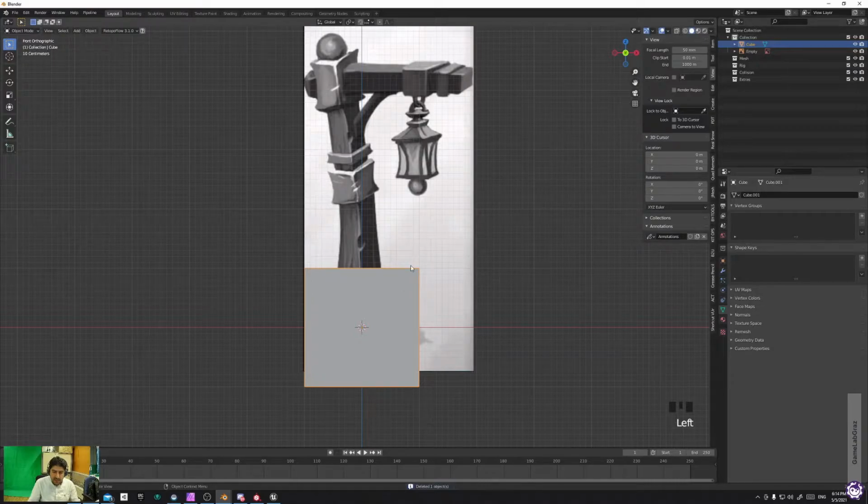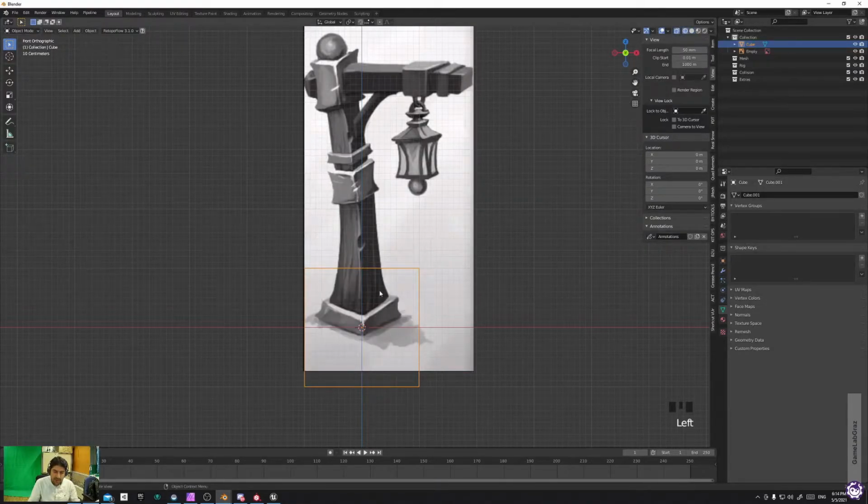The other point that is very helpful is going to the wireframe mode. That helps us also see behind the cube, to the picture. I think it will be very helpful in this case. The shortcut for it is Shift Z, to toggle between the wireframe mode and any other modes, either rendering mode or the other versions.